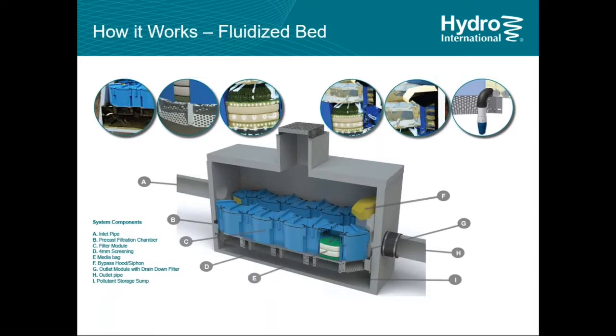That's pretty much the way this system operates. It's extremely simple, completely by gravity, and it's very versatile. What I mean by that is the driving head to run these filters can be varied. Typically, we use 30 inches above the media to drive water through it, but we could do it with 10 inches of head pressure above the media if we need to. How we would compensate for that would be adding more filter modules. So it's an extremely versatile system.